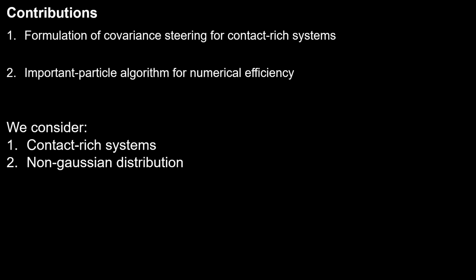Our contributions are as follows. We present a formulation of covariance steering for contact-rich systems using our proposed bilevel optimization using particles. It enables the user to formally assess the distribution of the state and contact forces efficiently. As a result, we can achieve stable long-horizon closed-loop motion of the robot with contact. Inspired by the cutting plane method in the optimization community, we propose an important particle algorithm for numerical efficiency.